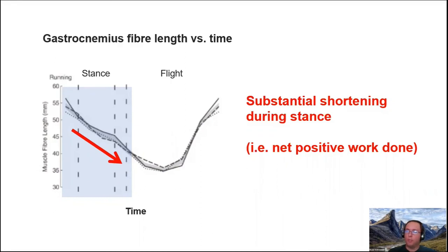And so that's why when we do these parameter variations, I think that's really the bread and butter of this sort of stuff, is understanding, oh, okay, if we increase this coefficient in front of the force rate cost, that motivates the model's actuator to want to do negative work and spread out these forces, right? So something like that I would consider to be a mechanism of the physics of that task. I don't know if that answers your question, but hopefully it does.